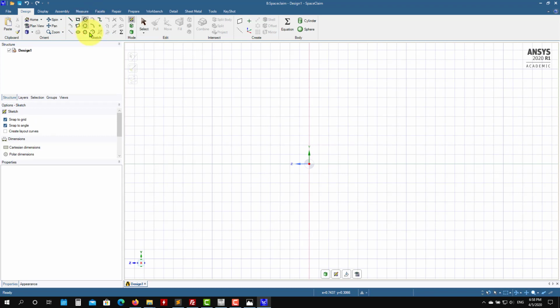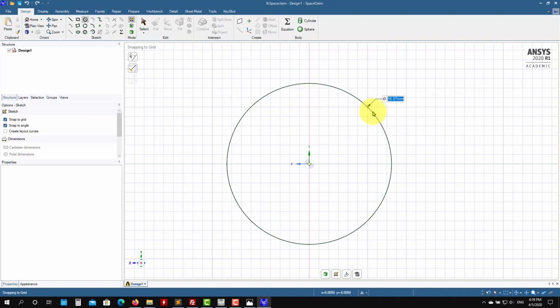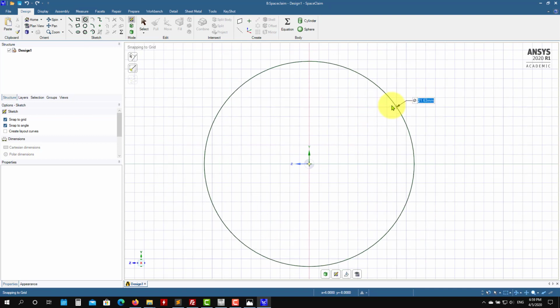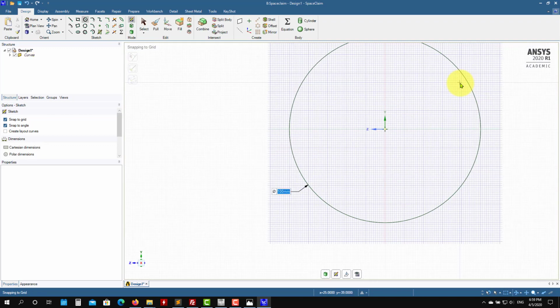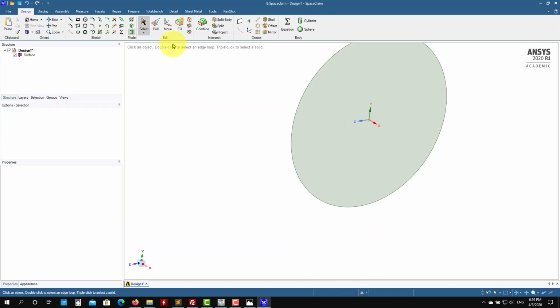And now select here, you see the sketch options. So here you have many options. So we are going to move in design. Select here. And then you just move to choose the dimension, or you can just insert it with the keypad. So my diameter will be 100. Okay, so see that you have diameter 100, and you go out. So when you go out, you have already the surface there, and now see here you have edit many options.